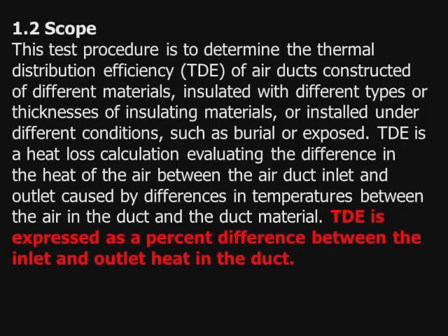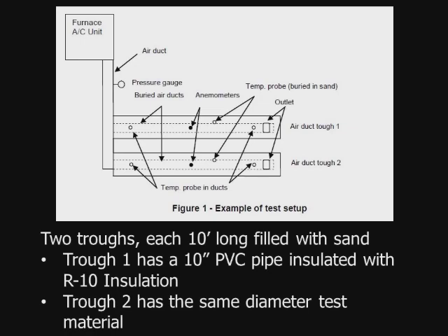This particular protocol looked to determine what the thermal distribution efficiency of air ducts were, especially when it pertains to buried ducts in the ground. Okay, you'll notice here that nowhere in the scope does it talk about R value. It specifically talks about TDE, thermal distribution efficiency. So what is this test comprised of?